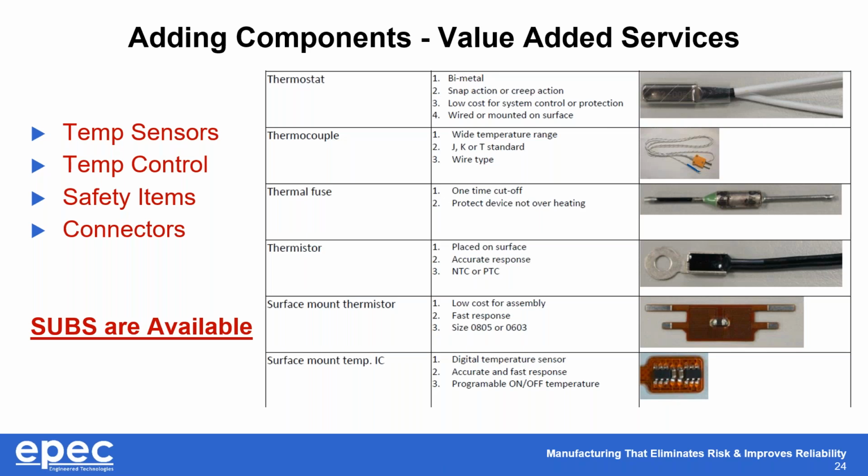A thermal fuse is used more to prevent against thermal runaway. Many of them are on or off and a one-time use event. The thermal fuse is there for safety. The thermostat is there to control it, and sometimes can be used in place of an auxiliary microcontroller or other way to control the heater.